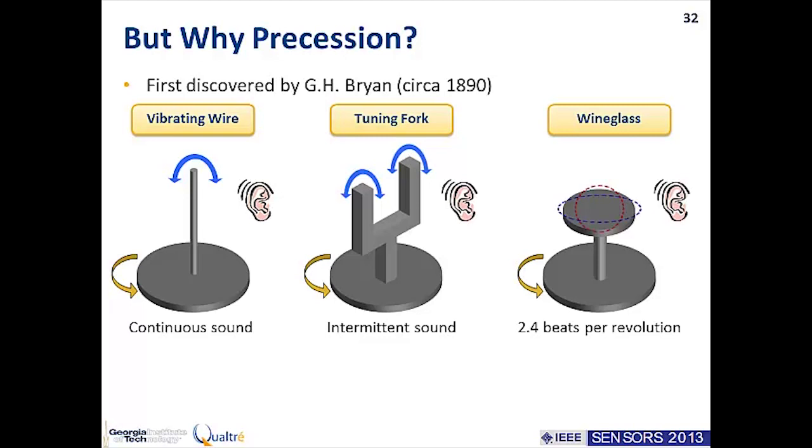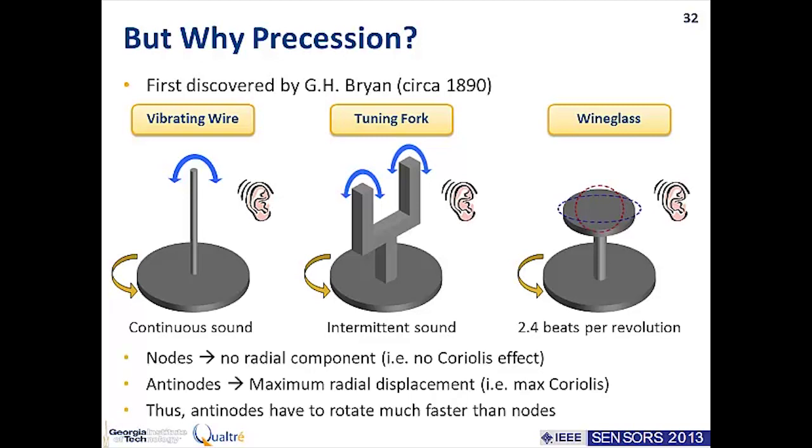And that's what really makes these shell type gyroscopes useful to measure full angle mode rotation. Another way in which you can describe this is that not every point in the structure perceives the same Coriolis acceleration. The points with higher velocity are going to experience higher Coriolis acceleration. The points with lower displacement or velocity are going to experience much less. So on average, you don't get the same amount of rotation.